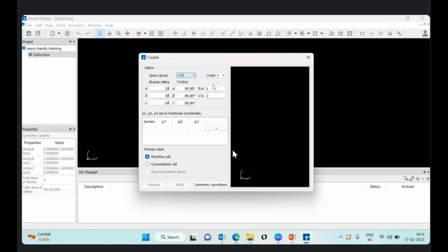It is not simulated. It will only be loaded in the interface. Then manipulation, doping, defect creation, all these things can be done once the material is loaded. All types of lattice options are there, either simple cubic, tetragonal, hexagonal, rhombohedral. These options will all be there with their symmetry operator information. Okay. This is just to create a new crystal from this window. Once you click on the build button, the new material can be built, or you can also see the preview before building.